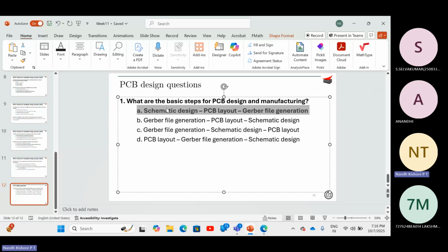Okay, so if you have to make a half bridge, you will connect the drain terminal of the top device to the DC source, and then you will connect the source of the top device to the drain of the bottom device, right? So that's how you make the connections. And after you make the connections in the schematic, you will assign the footprint, right? So if you have, let's say, a TO-247 package device for MOSFET, we'll tell that there will be 3 holes in the power board, corresponding to the 3 legs, drain, source, and gate. And then you will export it to the PCB and you will do the PCB layout, right? That is how the connections are going to look like actually on the PCB, right? And after that, you will create the Gerber file, and what you will give to the PCB manufacturer is only the Gerber file. So this is the workflow, that is schematic, then PCB layout, and then Gerber file, right?